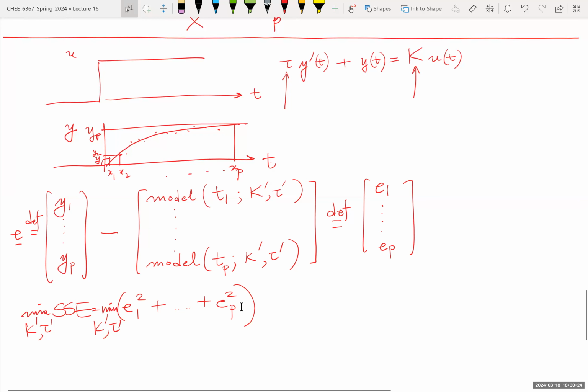So if you have software, it's very easy. You have a routine that solves the ODEs, that passes the solutions to an optimizer, which spits out the parameters k and tau. And it is done routinely these days. In fact, it's so simple you can even do it on Excel. It's not a big deal without using sophisticated software. MATLAB, of course, can do it routinely. Python can do it routinely. All software can do it routinely.